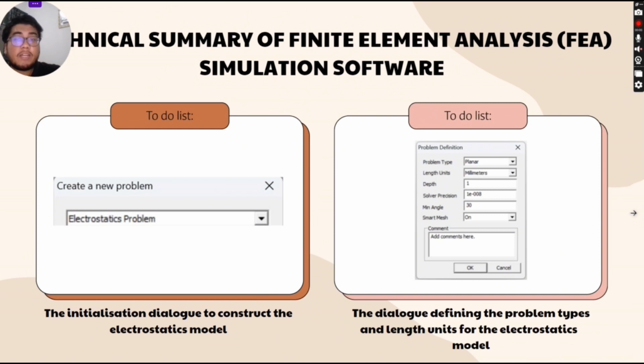Second, we need to define the problem type and the length units for the electrostatic model. For our problem, we put the type as planar, the length units in millimeters, the depth of 1, the solver precision is 1 with exponent of negative 0.008, the minimum angle is 30 degrees, and we turn on the smart mesh.